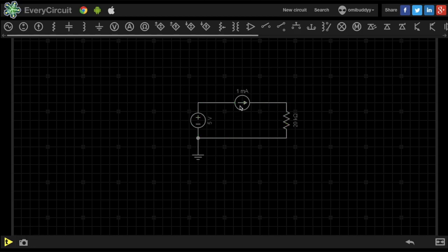However, there are two other possible cases which we could have done, which are putting a voltage source and a current source in parallel with the load resistance and the input source. If you put a voltage source across the input voltage, two voltage sources will get shorted, so this cannot be done. Another way is to put a parallel current source across the load resistor.